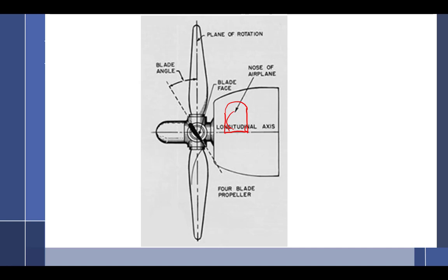And there's a dial in here, and it turns around with a little bubble in here. So what you would do is turn this until the bubble is zero here. Thing is, though, you can take this and just slide it over, and if you put it against the longitudinal axis, it would also read zero. So in reality, I don't use the plane of rotation because you can't find it. It's too difficult. But what you can find is the longitudinal axis. It's really easy to find.